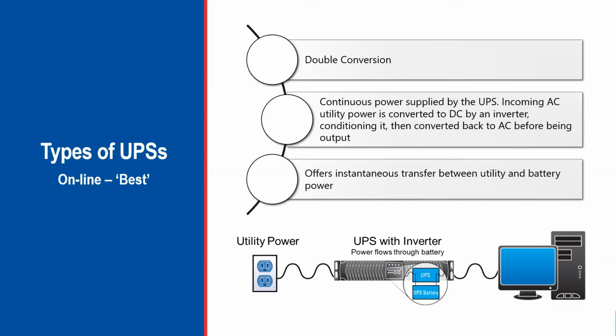Applications for these online UPSs do include medium to high density loads, ranging anywhere from 1 kVA to 20 kVA. These units are suited for enterprise-wide network systems, larger security systems, data centers, and industrial equipment. In addition, fire alarms and emergency communication systems are often required, both by local or state regulations, to feature some sort of backup power and offer extended runtime solutions.